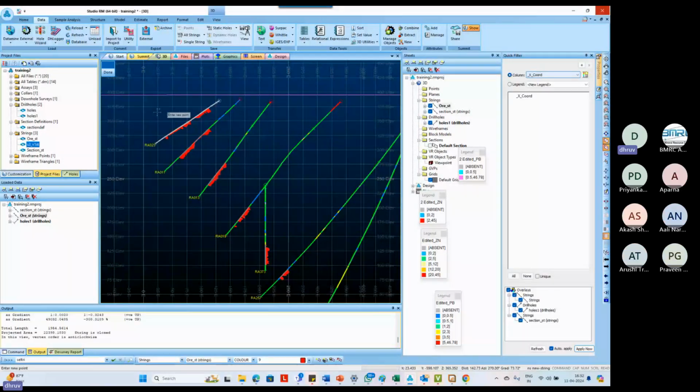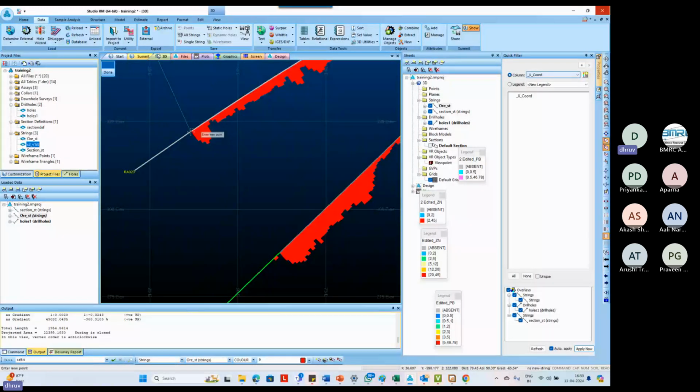Then what I'll do, I'll create a string, say NS. Now I will snap, but I'll snap in a wrong way. I would say it's a wrong way. So I'll click first. I'm clicking here, left click without snapping, same process. Now, because I want to use the intersection here, I'm snapping it here by zooming in, then right click. For snapping, you have to use right click. So I have right clicked it, then this zone, right click,